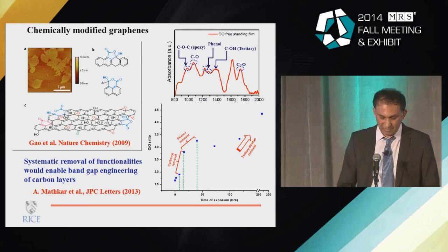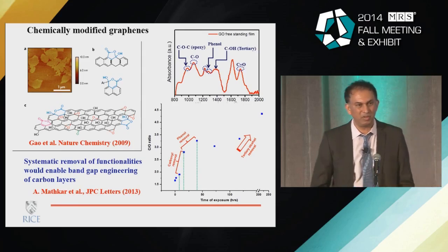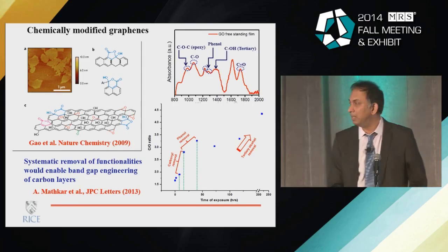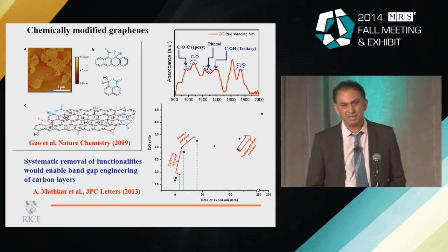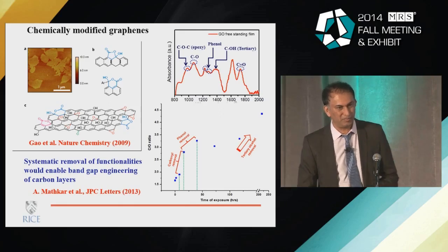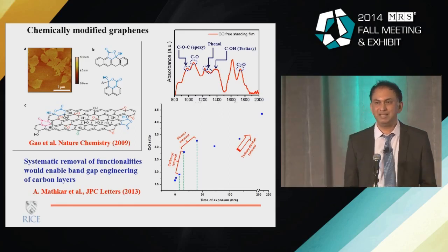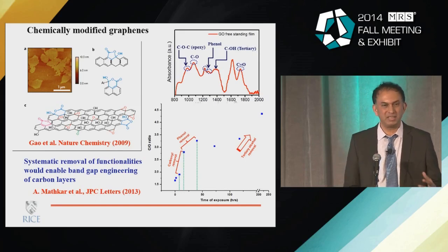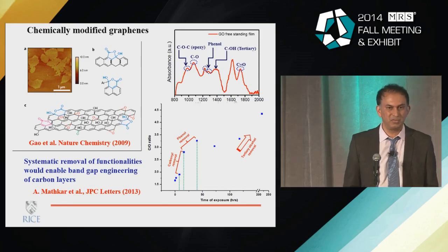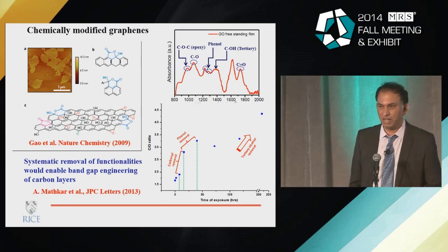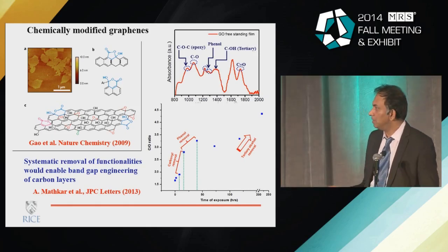Now, of course, graphene, so far we have talked about this pure graphene material, but also there is a large set of compounds that are based on graphene, but they have been chemically modified. And the simplest one would be something like a graphene oxide. You take carbon and oxidize, you essentially start getting all these functional groups onto the surface of these sp2 hybridized units. One problem with that is that typically, an oxidized carbon, oxidized graphite or graphene, is a very inhomogeneous structure. There's no real knowledge about how these functional groups are distributed on the surface of these units.